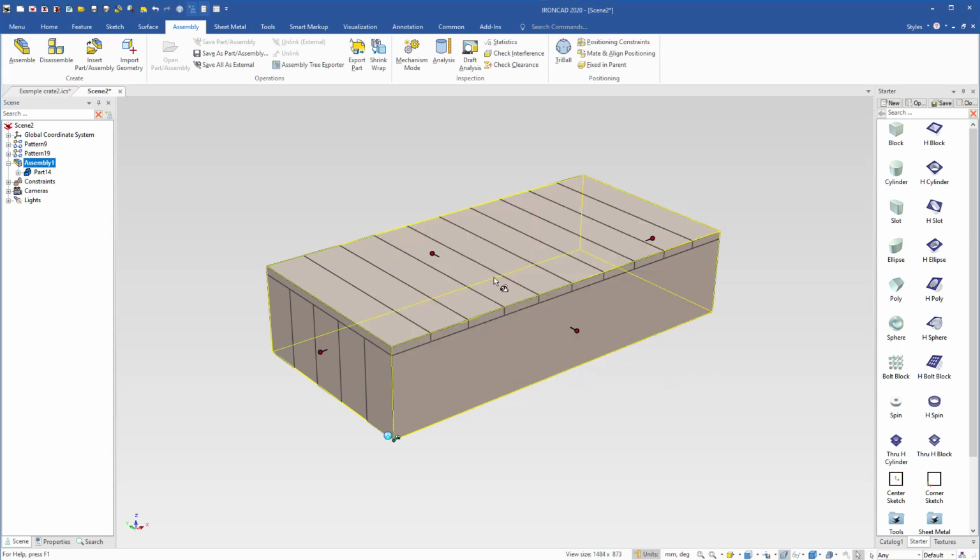And so what we're going to see is we now have handles on our assembly level. When we select that, if we select down to our box and even down to the block, you'll see all those now got controlled to be blue. And that's why we don't want these patterns to be underneath there when that happens, because it would reset all those parameters that we set up. So we only wanted to set just the block so that if I pull these handles, you'll see that block is going to change with it. But we haven't set anything else up to move yet. We'll get to that. Okay, so now we got the base of our handle set up to drive here.